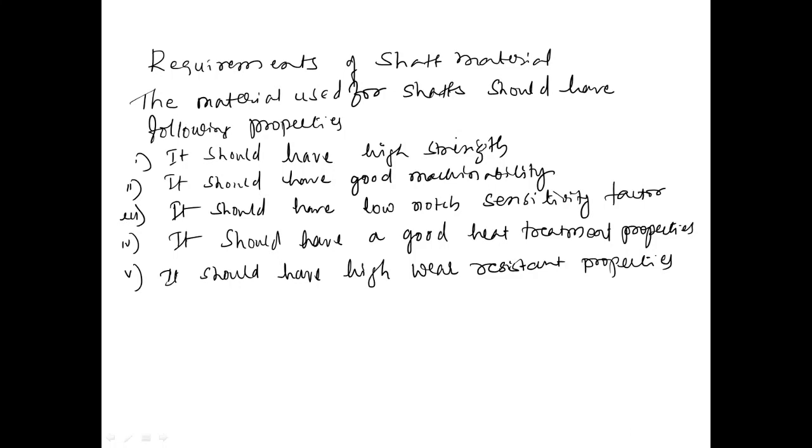As you're going to provide some discontinuity over the shaft for mounting purposes, you may cut the keys, drill the holes, or make some splines over it. As you're going to change the cross section, it is going to give some stress concentration. So it should give low stress concentration, which is connected with the notch sensitivity Q factor.